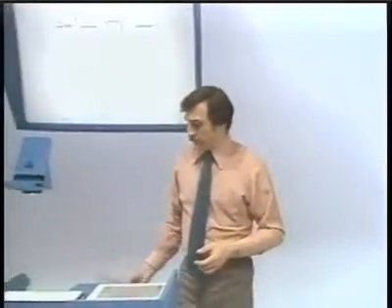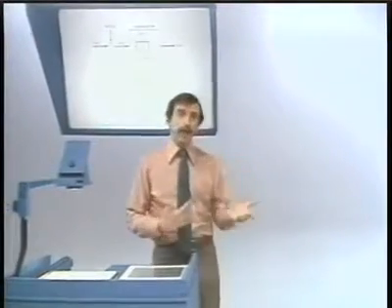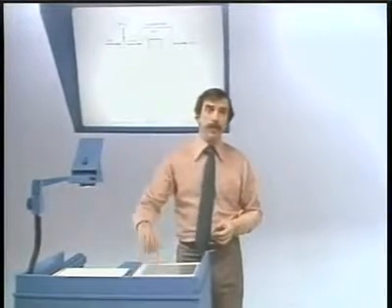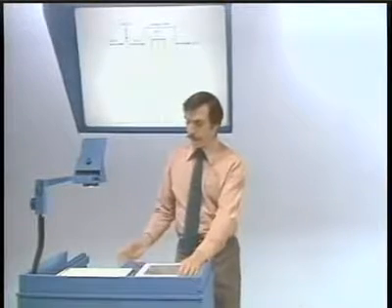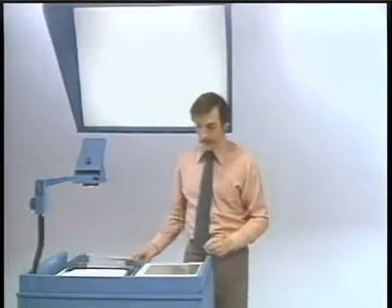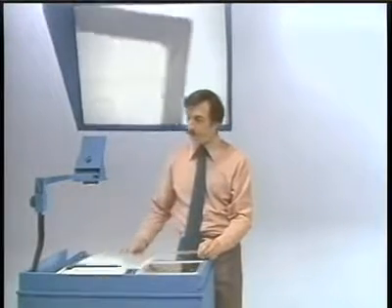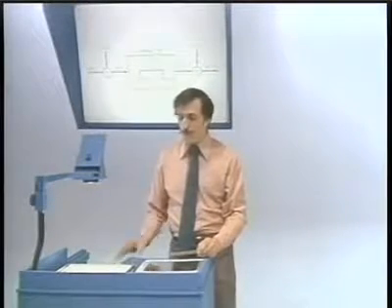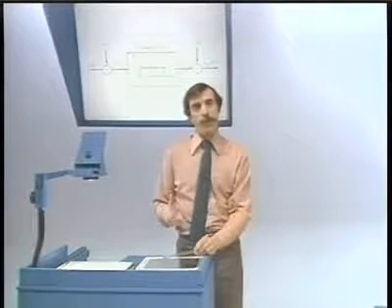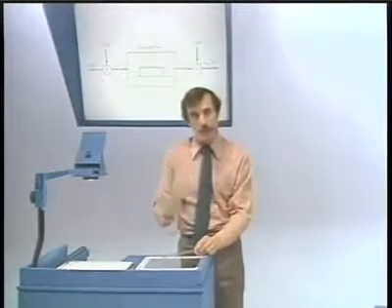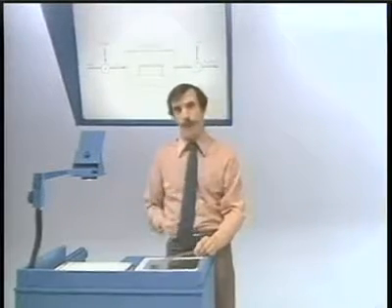Okay, now there is another application that we have discussed for both continuous time and previously for discrete time amplitude modulation with sinusoidal or complex exponential carriers. And let me just remind you of that because it becomes a very important one in the case of discrete time systems. And that is the notion of using modulation together with fixed filtering to implement a filter which either has a variable cutoff or converts, let's say, a low-pass filter to a high-pass filter.